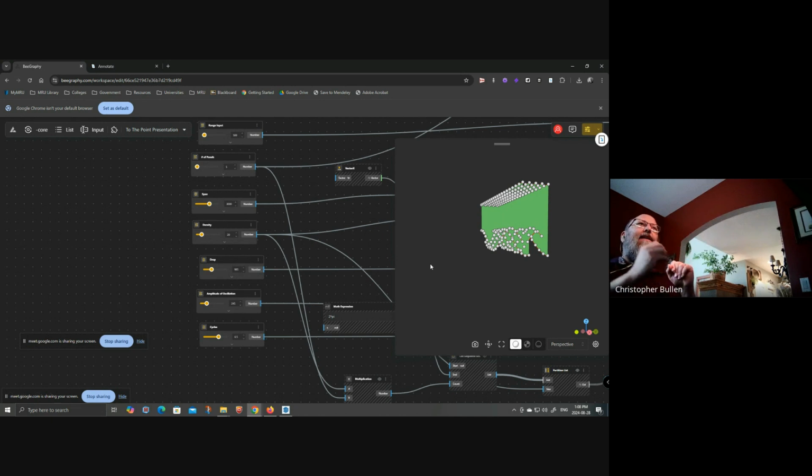So first of all, let's start by creating a list that we can use as a successive drop from the first panel to the next panel to the next. Now we've got a problem. The first is going to remain at whatever the drop height is for the panel. The second one, let's say we want to drop that a half a meter. So we want to go 500 down on the next one. The next one, we want that to go down 1,000 from the original drop height. The next one's going to go down 1,500 and so forth. So we need to be able to incrementally add that to each one of those partitions, each one of those lists.